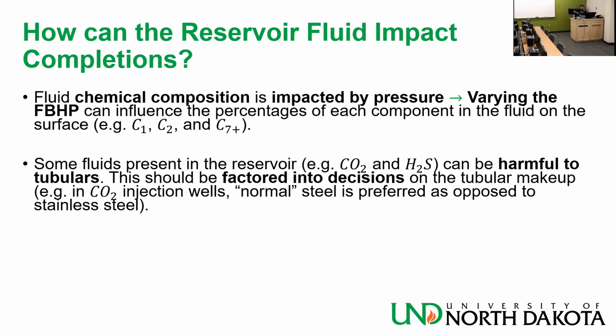Those wells, they found that normal steel doesn't corrode as fast as stainless steel, which is a weird phenomenon. But if you plan to inject CO2 from that well, you better make sure that everything in it can handle what you're going to inject.